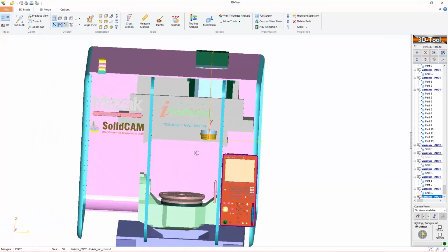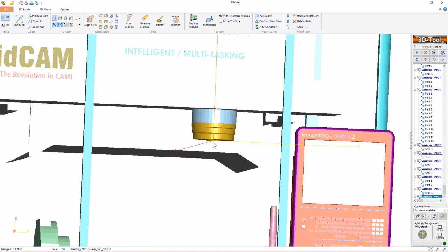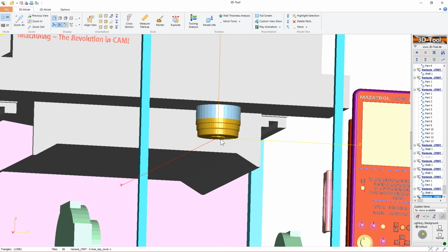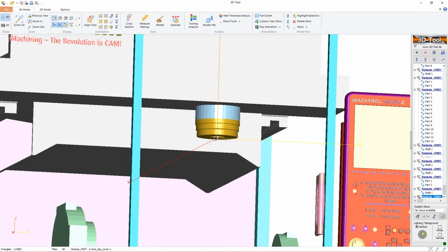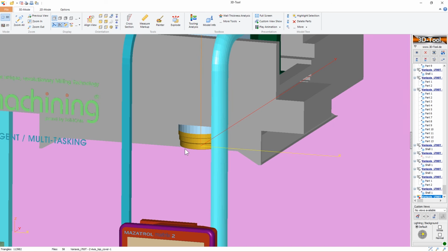You will note one thing here: the spindle itself is located in machine 0. I didn't mention this, but the coordinate system of the STL files is located in machine 0, and our spindle is located at that point. So I'll choose this as my home reference point. Therefore, the home reference for all my axes will be 0.